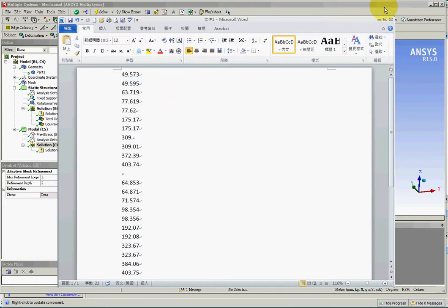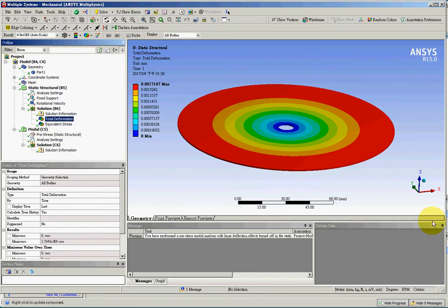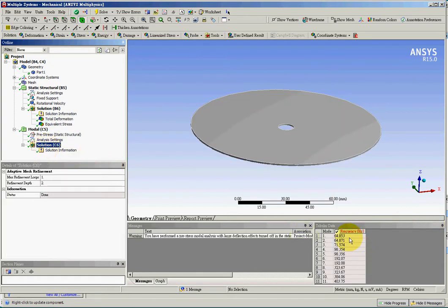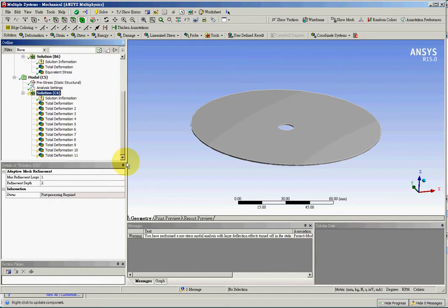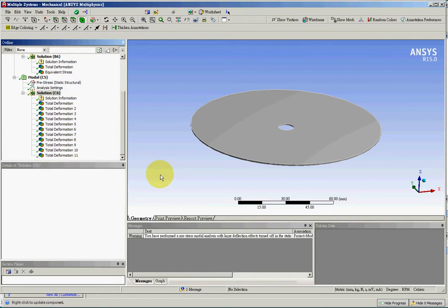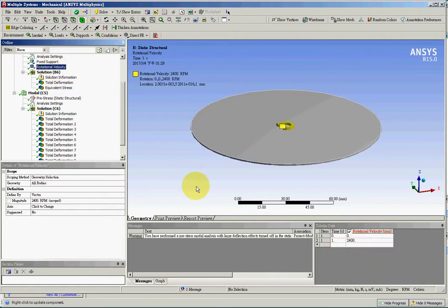So we found that when you use higher rotating speed, the result will be higher frequency. Natural frequency will increase with increasing rotating speed. And as I said before, that external force does not affect a natural frequency of a structure, but rotating speed is actually a form of external force. But how does it change the frequency of a structure?